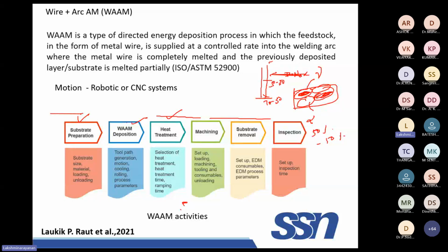Because of the cooling rate. Here it is a substrate. Whenever you deposit a wall, the heat will be extracted through this. All other places are through only radiation. So naturally there is a thermal gradient from the top to bottom, and that will affect the formation of the phases present. So this is a microstructural heterogeneity. Naturally, the properties also will be different at different locations. If that is the case, you need to go for heat treatment.